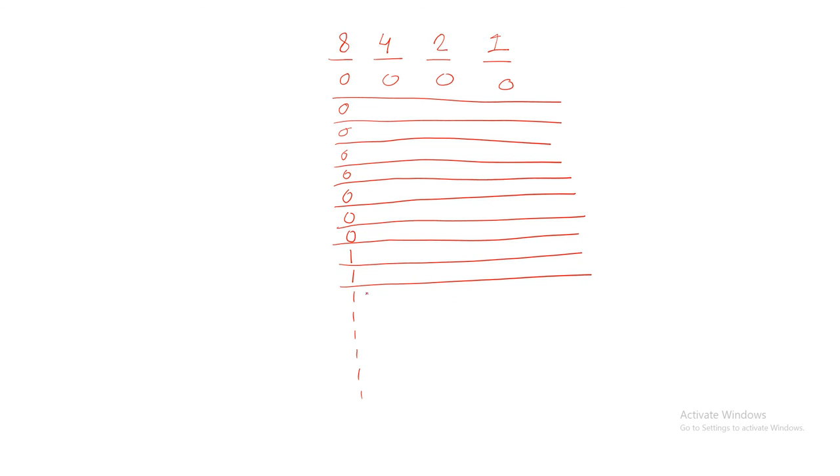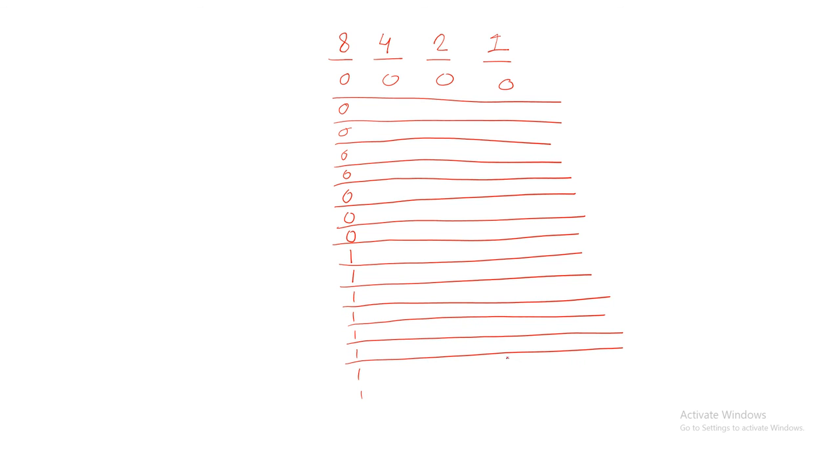Now it is a very important concept and we will be using this rapidly, so you need to be very familiar with it while writing the possible values. The maximum number of bits that we will be dealing with is 4. So the MSB should be altered after 8 values, the next after 4 values, the next after 2 values, and the last after 1 value. So four 0s, four 1s, again four 0s, four 1s.